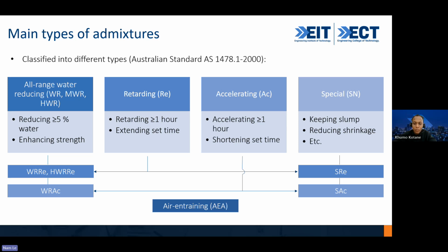It means typically we may need 5 or 6 hours for concrete to set or harden, right? But the accelerator makes it faster. For example, around 3 or 4 hours, it can set. It means you can reduce the waiting time, so that you can have earlier strength of the concrete, or a shorter waiting time, right?